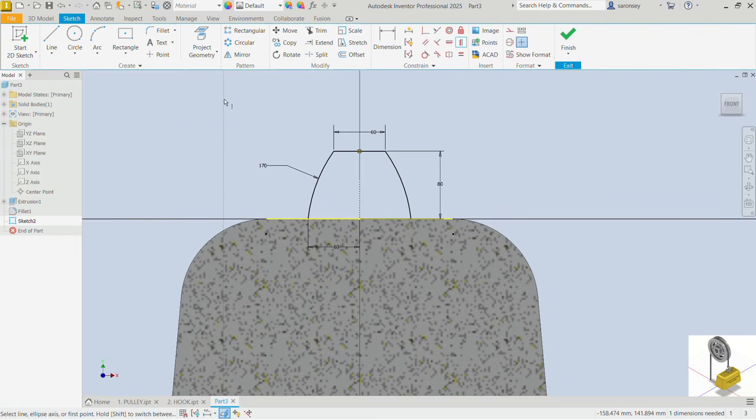Let's even apply some fillets. So let's pick the fillet command. Let's do a fillet radius of 30. Let's see how that looks between this arc and also this line. Will do same on the opposite side, but 30 is a little bit too much, so let me reduce that to 20, and we would enter. Okay, I didn't reduce it. Let me double click actually from here and reduce that to 20 and press enter.